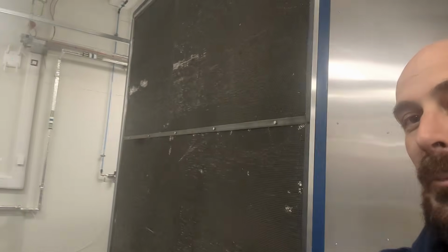Right, so here we are in the wind tunnel lab in the Department of Mechanical Engineering in the University of Sheffield. So you can see the wind tunnel behind me. So the basic principle of a wind tunnel is pretty simple. You've got this end where the air gets sucked in through this grid, which if you look close you can see is an aluminium honeycomb. So the purpose of this is to straighten the air.